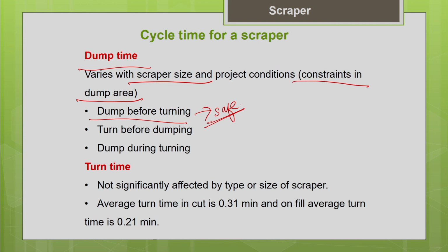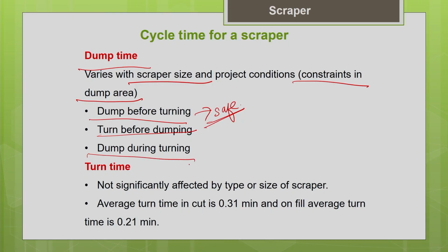In some cases, depending upon your project site, you can see that it will turn before dumping. That means it is turning in the loaded condition, which is relatively unsafe for the scraper. Sometimes you can see that your scraper will do the turning and the dumping together, so that will actually increase your dumping time. So there are different ways to do it. Which way you are going to dump depends upon your actual project space constraint.